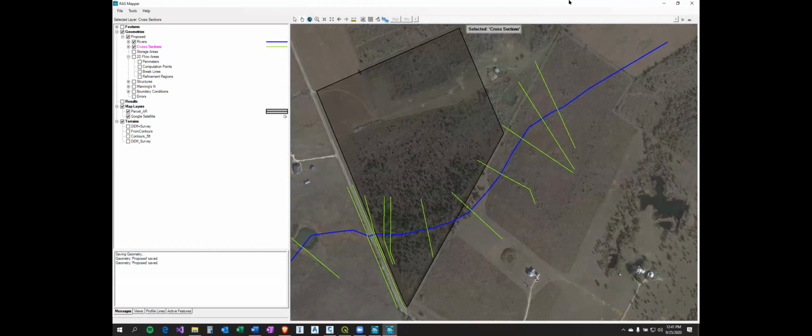You need to be doing your work inside of HEC-RAS if you can, the actual simulation and analysis. Civil 3D is where you're going to do your maps and produce your exhibits. You're going to create line work to use on your construction plans, and RAS is going to export those types of flood boundaries and even velocity grids. It can give you all kinds of stuff, but in the end, you're going to dump that back into a GIS or CAD program. For this presentation, we're talking more CAD side, but that's my recommendation. I would not get into the river analysis software at all.